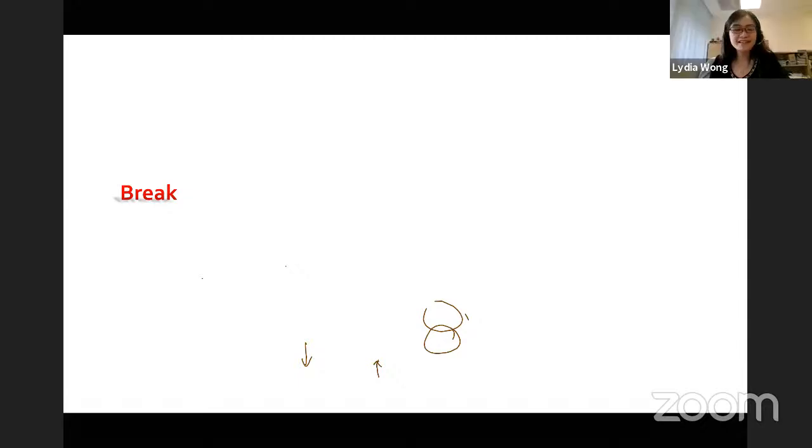Very good question. And actually it's a long answer, right? Let me try to give you a short answer. There are a lot of clever ways to do this. In the first generation of solar cells, you probably have huge electrodes, so that you can control the area, the width of each of these metal lines. And as the technology advances, this width is getting smaller and smaller. So that is minimizing the shading.